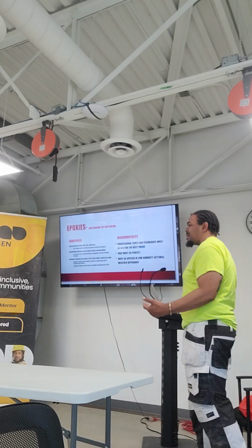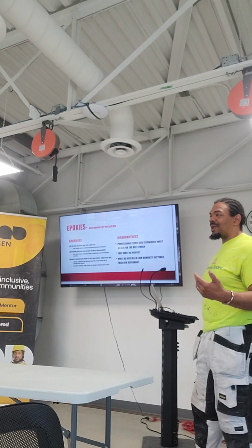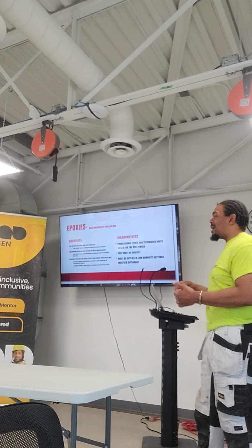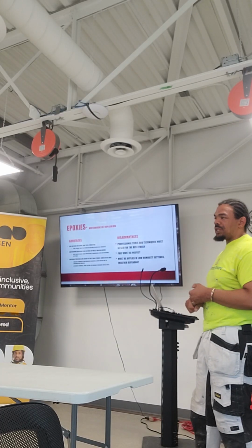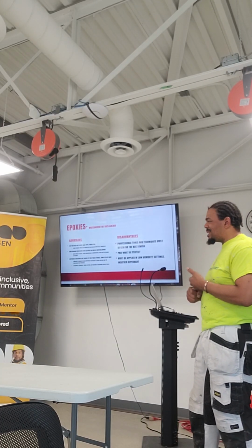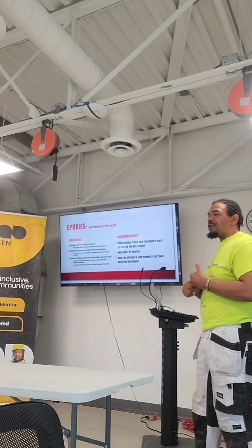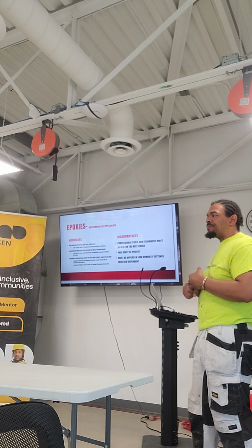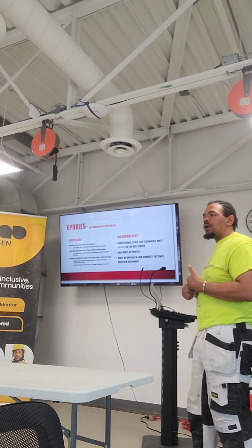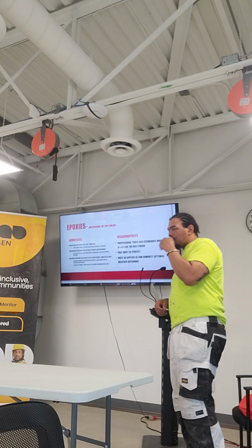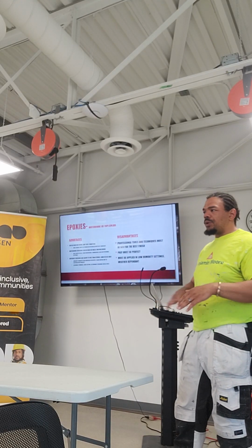Some of the disadvantages to using epoxies, and a lot of people don't like them, are that you need professional tools to do it correctly. You need to have the prep done absolutely correctly. You cannot skip on the prep. You have to be very, very astute in how well you do your preparation. For instance, when we do epoxy floors, we grind the floors down.